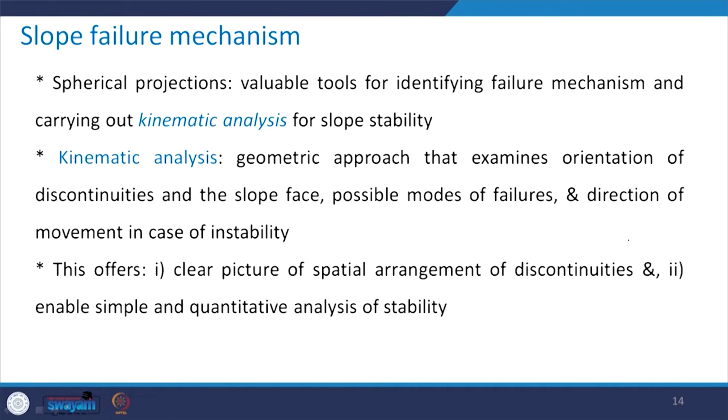And they are helpful in carrying out the kinematic analysis for slope stability. What do we mean by kinematic analysis? It is a geometrical approach using which we can examine the orientations of the discontinuities and the slope face, the possible modes of failure, and if there is instability, then the direction of movement.